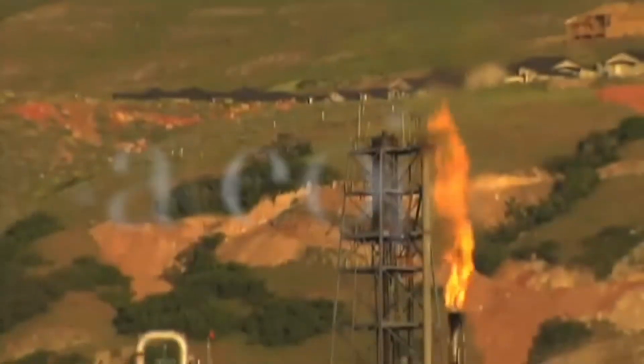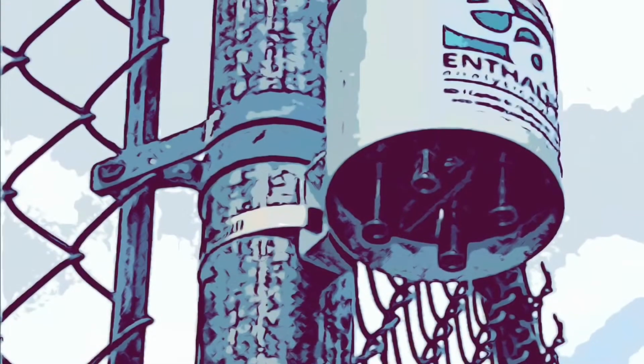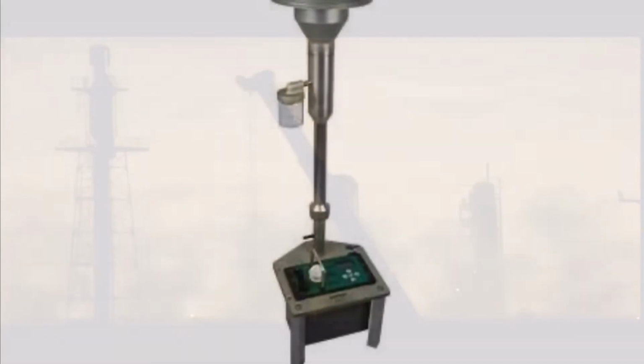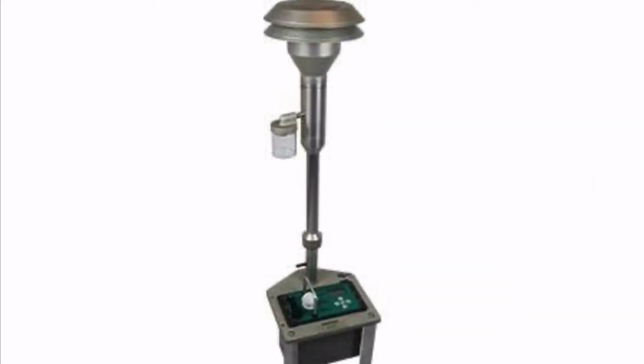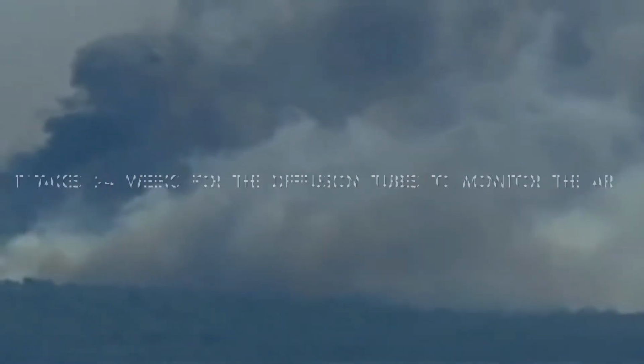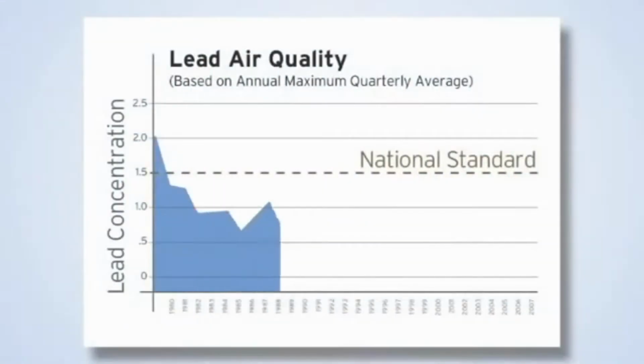Passive monitoring happens when diffusion tubes take in a particular contaminant from the air. No power supply is required. It takes 2 to 4 weeks for the diffusion tubes to monitor the air. The tubes are then taken to the laboratory for examination to determine the number of contaminants detected.